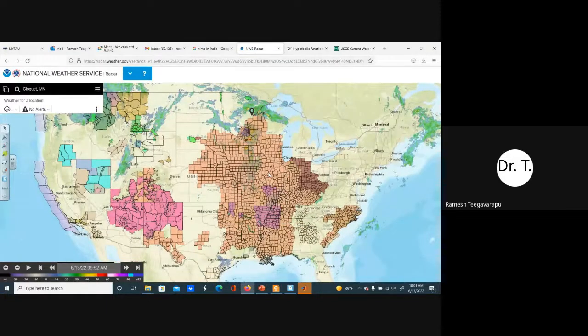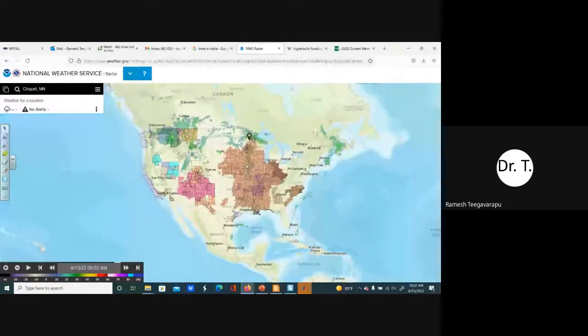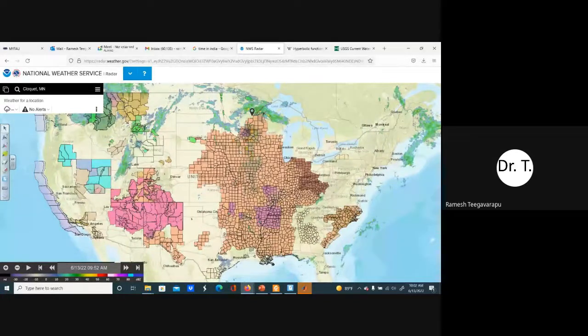And we combine them with other data sets like rain gauges, other sources of privately owned radars, privately measured rainfall amounts, volunteer-based rainfall amounts, and then they combine all of them. They come up with a product which is reliable, and they provide that precipitation data to regional forecasting centers, and the regional forecasting centers run their simulation models to quickly come up with numbers, especially the stage thresholds, to give warnings to people about flash floods, and any impending flooding which might happen in the next 2-3 hours. That kind of information is available.